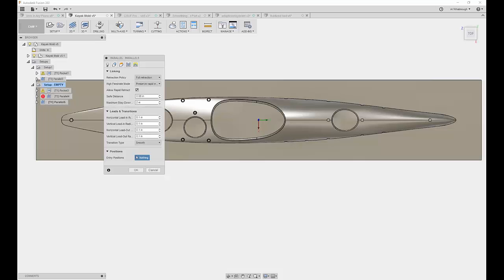I'm curious to hear what Rob said, some of you guys. I think Keith's an expert on this today. Feel free to put in. But at 50%, you're saying that the stay down distance is exactly the same as the rapid distance. So from that, you know it's going to be something less, and then it's a factor of what's my feed rate difference and what's the decel impact on that.